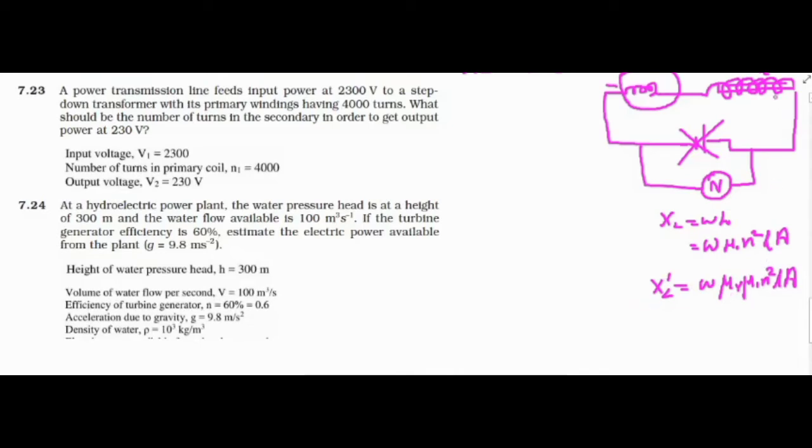It will increase the impedance of the circuits. When impedance increases, so we can see XL increases. When XL increases, Z will increase. When Z increases, current I decreases in the circuit. As current I decreases, the brightness of the bulb decreases.